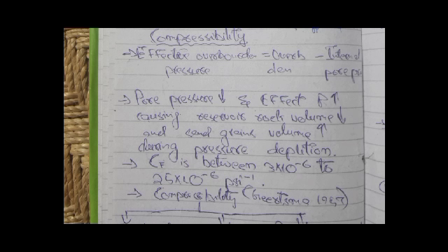In that condition, pore pressure decreases because fluid is going, so there is nothing to face the overburden pressure. Effective pressure is increasing because no more resistance is coming on its way. And reservoir rock volume decreases because of the collapse of the rock due to the traveling of the fluids within the rock outside. As the fluid has gone outside, we do not have the same rock volume anymore.